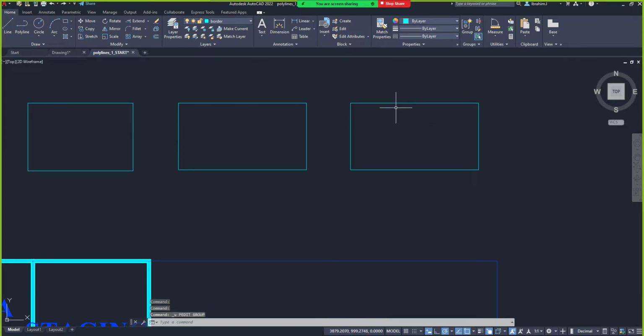I'll Ctrl Z. Can you see my line is segmented now? What I want to do now is I'll select a line out of the shape that I'm trying to group together. I'll go to my modify tool, go to my P-edit, which is my polyline edit. Now it's asking me that question again. Do you want to turn it into one? I'll click on Y, I'll click on enter. That's yes, enter. Then I'll now go to what? Join.